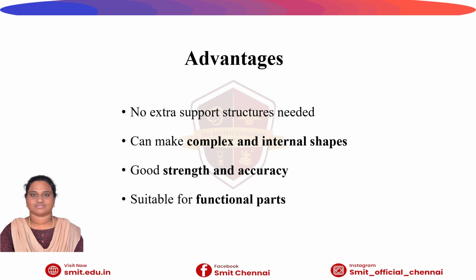Next, the advantages. The granular based 3D printing offers several important advantages. Since the unused powder surrounds the part during printing, no extra support structures are required, which reduces the material waste and post-processing. This method allows the production of complex geometries and internal features that are difficult or impossible to make using conventional manufacturing. The parts produced have good strength and high dimensional accuracy due to precise layer by layer fusion.